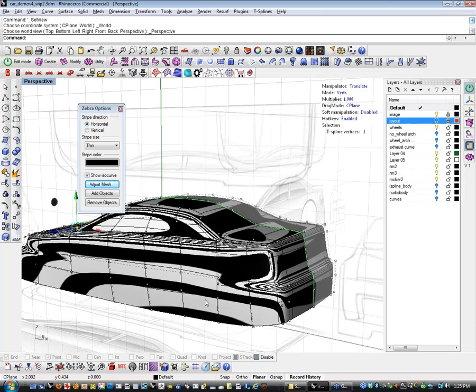And so I would either use a Faro arm and pick enough points that you could build the surface that you're building off of, or quite honestly, if someone was paying me to do that, I would rent them an Ulta scanner, a red light laser scanner, and do a full-blown scan of the rear trunk, have the thing in there, so I knew that I was dealing with the exact holes and the exact position and all that kind of stuff, and then just build your T-Splines part off of it, and then use the reverse engineered surface to Boolean out of what you finished making, and it should fit like lasers.